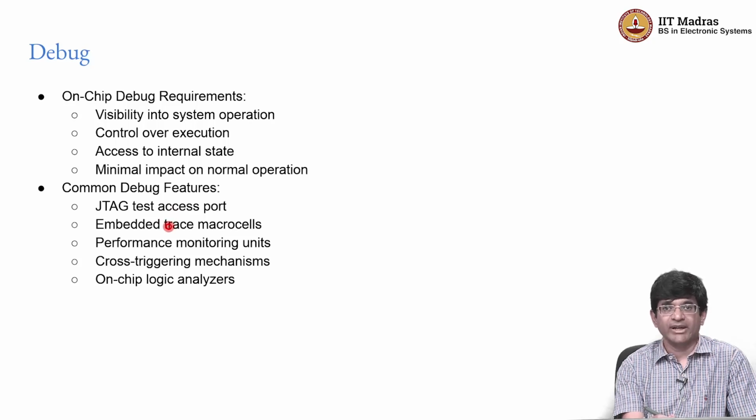Of course, it has to be designed this way. So while you are designing it, you need to make sure that the JTAG chain has also been integrated into the design. But once it has, it allows you to go for really in-depth capture of individual registers present inside the system.